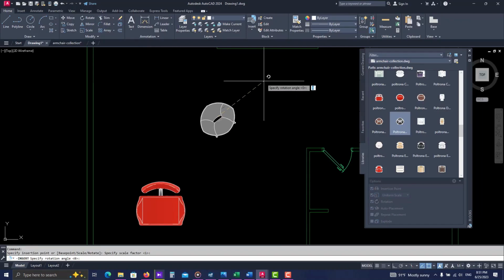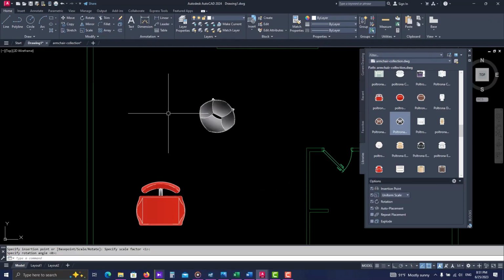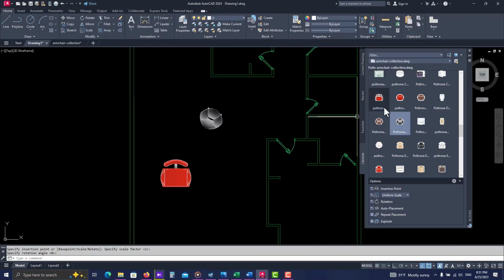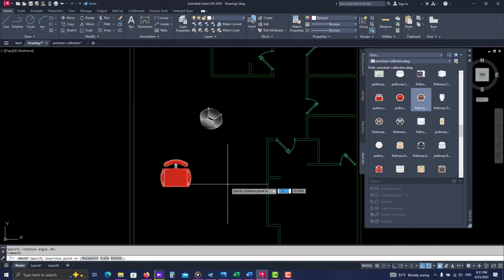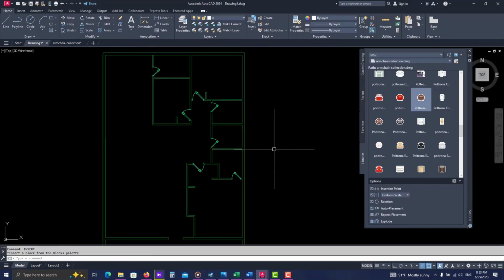Watch this. Firstly, we specify the scale. Secondly, we specify the rotation angle. Then when we click or press down enter, it will be finalized and saved. So here we got some options while we are replacing these blocks, like rotation and scale, as I showed you. In the continuation, I want to tell you how to convert the blocks, or block replace.